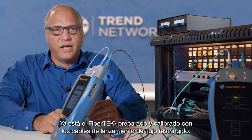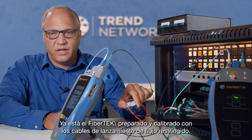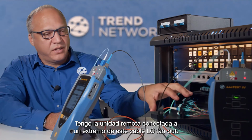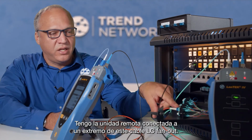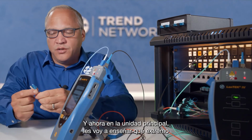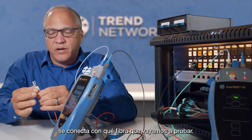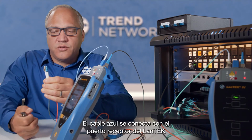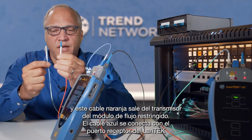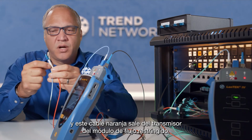So we now have the FiberTEK set up and calibrated with our encircled flux launch cords. I've already got the remote handset connected at one end of this LC fan out cable. And on the main end, I wanted to demonstrate to you which end should go on which fiber you're testing. The receive cord, so this blue cord, is going to the receive port of the Lantec, and this orange cord is coming from the transmit port from the encircled flux module.